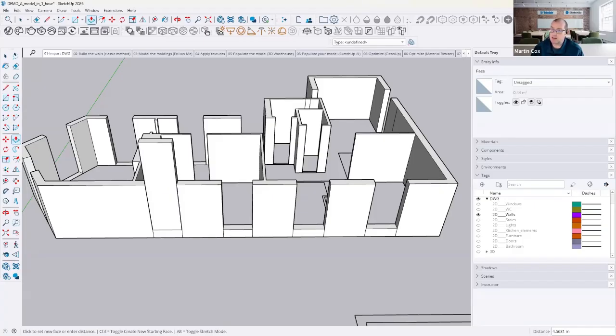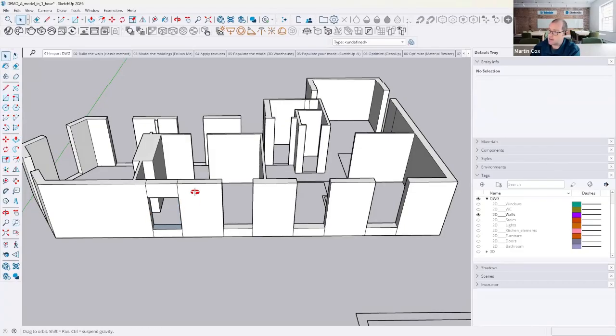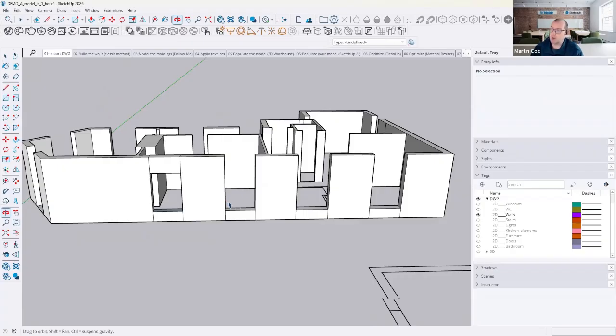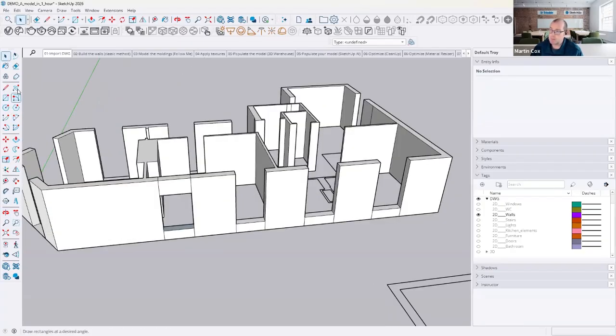So we can start to see that window there, and I can specify that. I'm going to say 1.8 meters. And then again to the top there, I can match that. So we've got those options, and I can select my window, delete that face, delete the face inside, and we're starting to put together those windows.